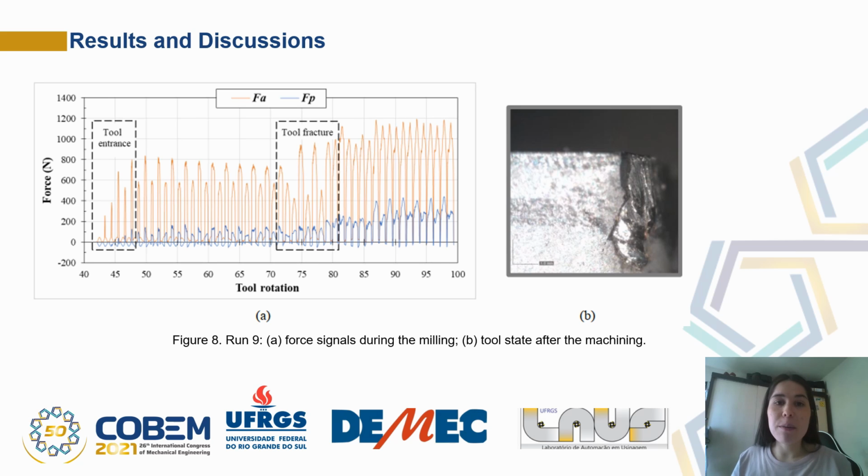In this case, the dynamic portion was higher than the static portion by 102% for active force and 296% for passive force. Soria explains that the lower the depth of cut to nose radius ratio, the greater the force in the axial direction. That tends to push the tool away from the cutting region, tending to increase vibration.